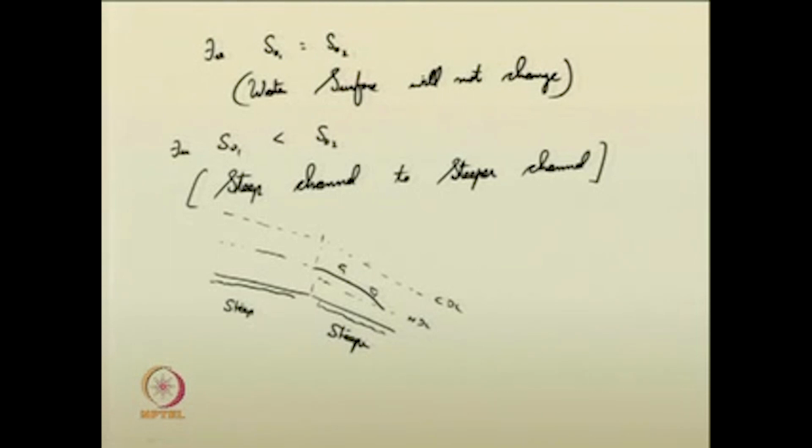So, this is having an S2 profile. This is the only profile that is possible when a steep channel is followed by a steeper channel. Okay. So, S2 is the only profile possible. All other things are theoretically not possible. You can verify yourself.